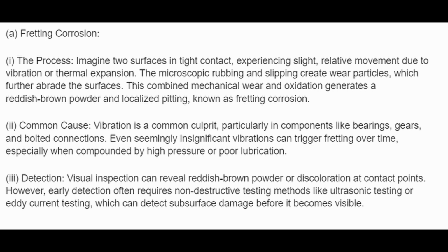2. Common cause. Vibration is a common culprit, particularly in components like bearings, gears, and bolted connections. Even seemingly insignificant vibrations can trigger fretting over time, especially when compounded by high pressure or poor lubrication.